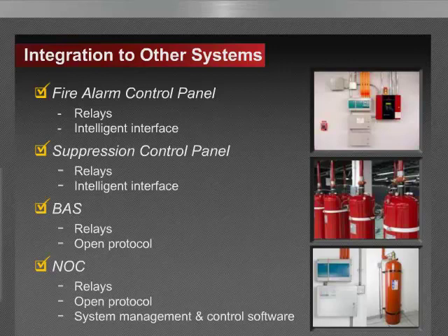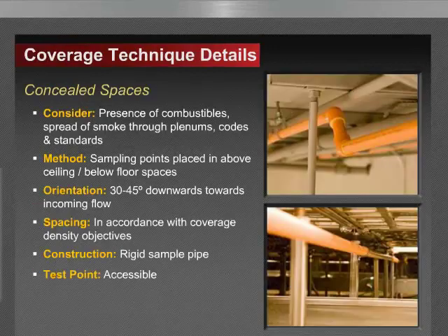Great, thanks. Another question, for those who use NFPA 72 frequently, we're well aware of the changes that have occurred over the last couple editions that have to do with things like beam pockets, waffle ceilings, and so forth. And you addressed those briefly in your presentation. One of the attendees asked whether sampling points need to be located within 4 inches of a ceiling where solid beams exist throughout the area, or can those sampling points be located at the bottoms of the beams as allowed by NFPA 72 for spot detectors?